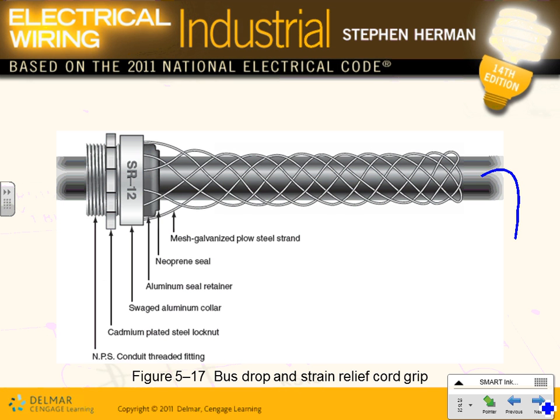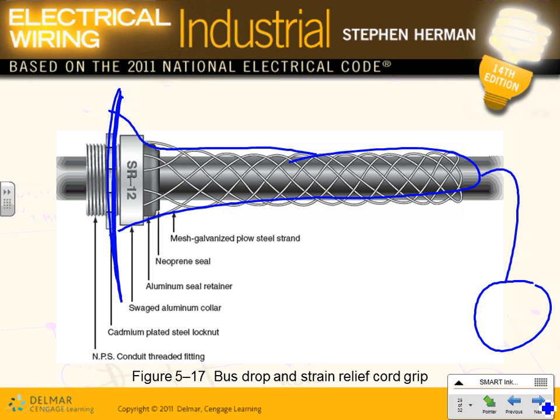So long story short, here's what you're looking at. As you tie this down, say 20 feet, and you tie to the equipment, the weight of the cord is going to be supported from right in here. Can you guys see that? How it grabs on the cable and supports, the weight will be supported by the box, not by the connectors. Otherwise, we'll be pulling on the connectors. The last thing you want to do is have hot connectors and you're pulling, the weight is supported from the electrical connectors. So anyway, typical that you support your cord. So when you're a project manager, Kerry, that's what you're going to be paying attention to when you put your SO cord.